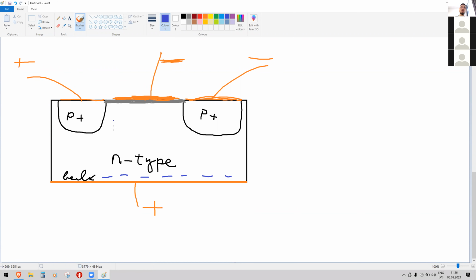So electrons from this material run away to bulk. And since they have deserted this region, it becomes somewhat positively charged. Some electrons just jump out of their atoms and run to this other end of the material. And so some ions of material stripped from electrons stay there, they are charged positive.